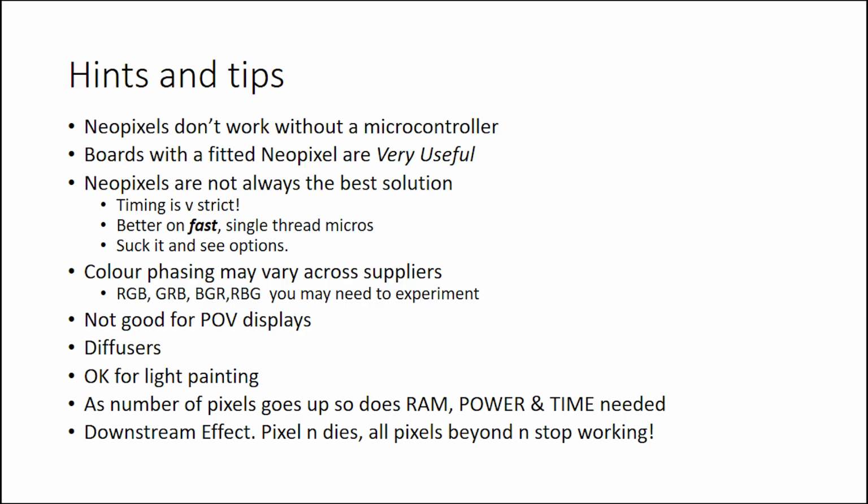You're looking at a frequency that's 0.8 of a microsecond and 0.4 of a microsecond. If your lines can only go up and down in 0.7 microseconds, you ain't going to be able to drive that. And even if it's 0.113 microseconds, you're not going to be able to get 0.4 microseconds out of holding it up for 1.3 microseconds. You can have 3.9 or you can have 5.2. You can't get the 4 sort of thing. So you have to sometimes think about the frequency that your microcontroller's running at.